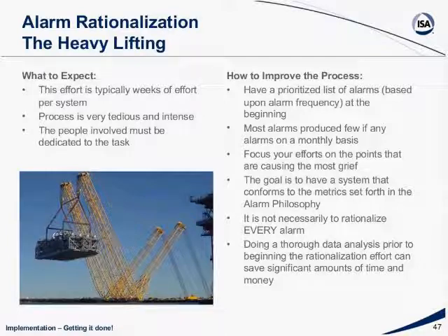And so you want to make sure if you catch something like that, you address it right away. Everything needs to be done on a consistent basis. So double check the engineering units on that. But focusing your efforts here in rationalization, and having that whole prioritized list, can really get you to your targets, your metrics, quicker than trying to do the whole thing in one fell swoop.